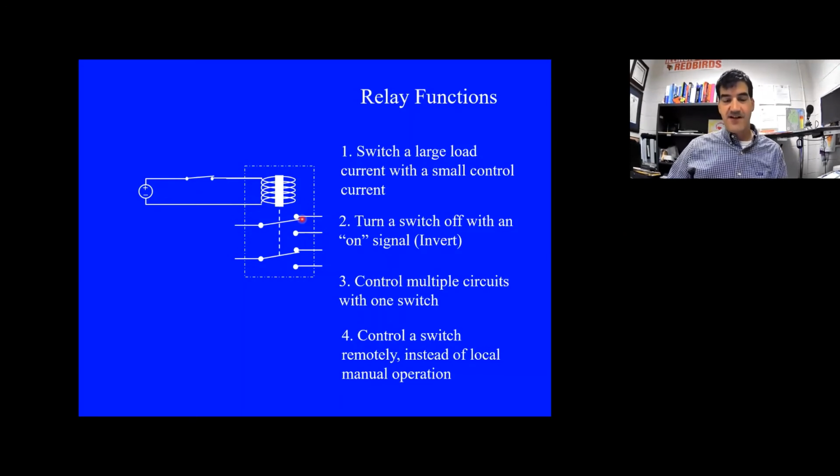That's more dangerous, and there's a greater chance for arc flash to happen, like we talked about in electrical safety. So ideally, when you're making this switch, you don't really want to be standing right next to it if you can help it. Much safer to be in a different room. So you can control this part of the circuit in an operator station, different room, and you could have the actual switching of the loads, which is this part, in a different room. You'd have the whole relay in a different room, and that's just a safer way to control large, high-power devices.